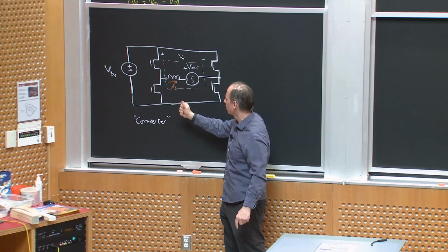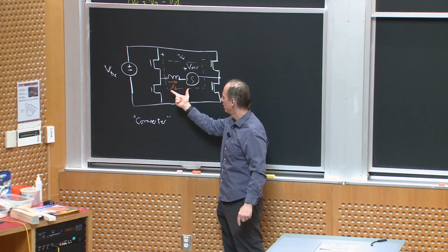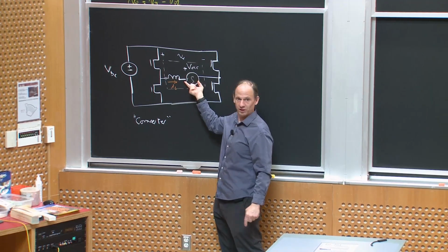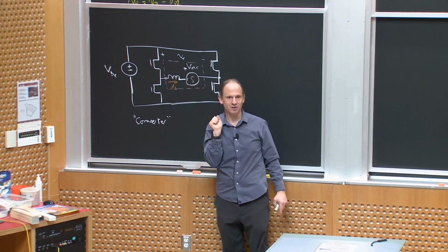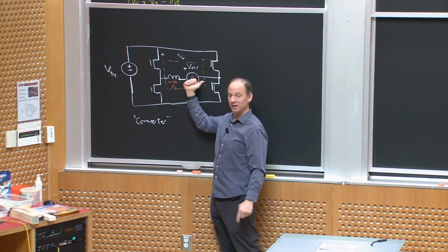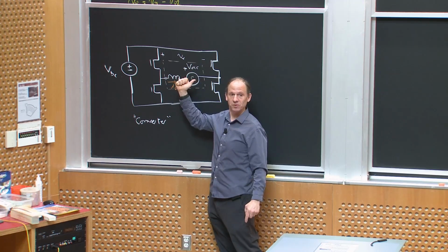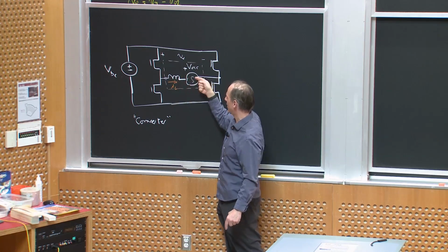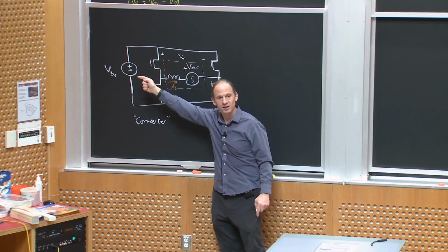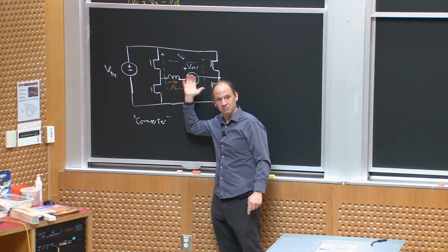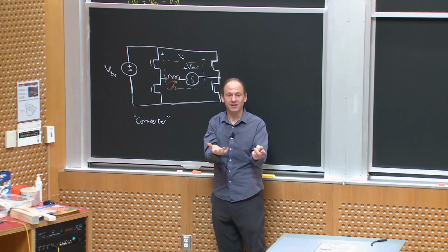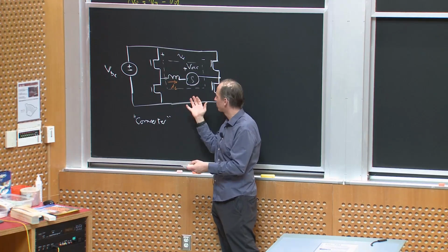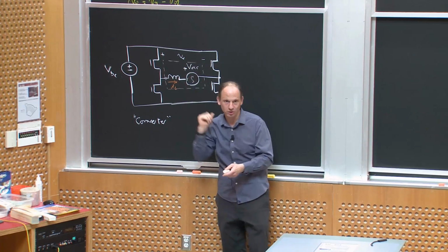So really, it's a question of whether power is flowing AC to DC. It's just me deciding, relative to this voltage, what I want the phase of that current to be. It could be exactly in phase, and then I'm purely delivering DC to AC. IL could have the exact opposite sign to VAC, and then I'm purely delivering energy AC to DC, or something in between. So yes, exactly how I control the switches determines the power flow direction in this generalized picture, understanding that there are limits on what the load can do.